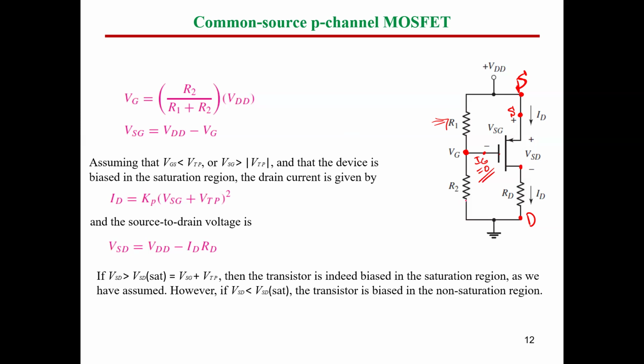So once you turn it on, the DC steady state current is going to be 0 for this MOSFET, but you will have VGS all of the time if the MOSFET is working either in saturation or linear mode. So there will be a value of VGS all the time and IG equals 0.